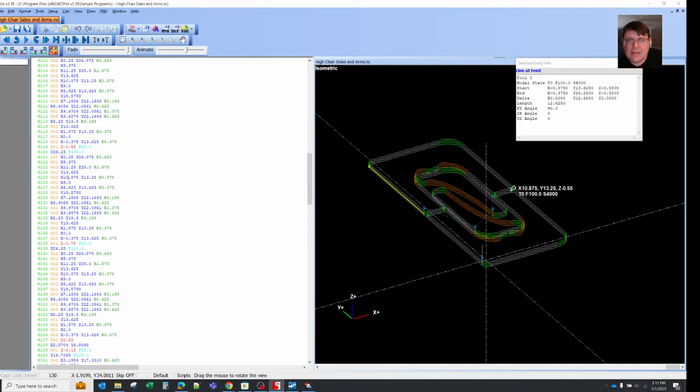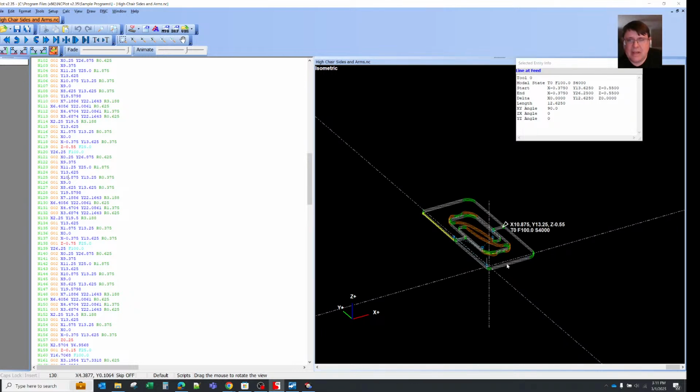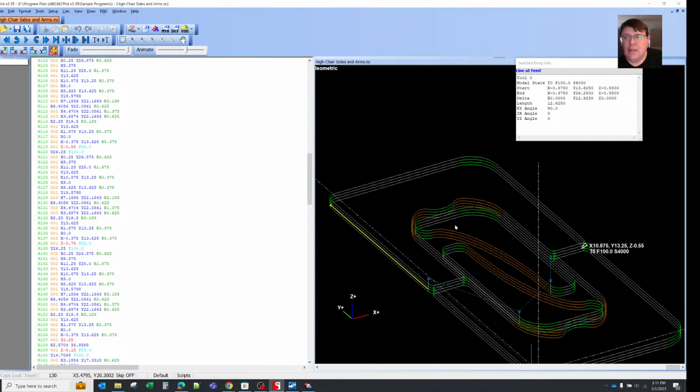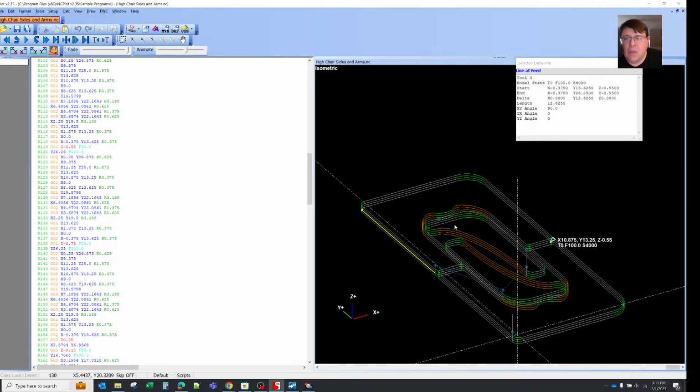Also, if you make edits to the code, you can see those edits visually, and you're not working at the CAD CAM level, you're working at the NC level. And it's all well and good to say, okay, in our shop, every new program is going to originate in CAM software, and we're only going to edit it in CAM software, and that's all we're going to use. But the reality is, I've worked in a lot of different places where you're coming in and all you've got is this G code program, and you don't really have access to anything else.